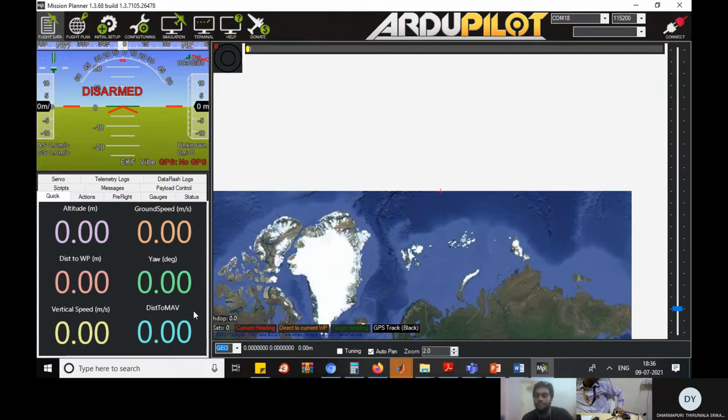If your satellites are distributed in different directions or different areas in space, then the volume will be very large and your DOP will improve. Mostly the DOP will be 1 to 2, and this will show the number of satellites. Based on that, you can check the accuracy. So 10 to 12 satellites are supposed to be detected every time during your flight.